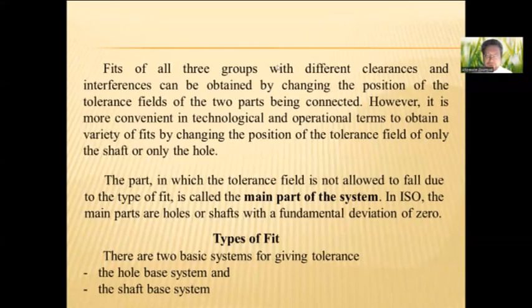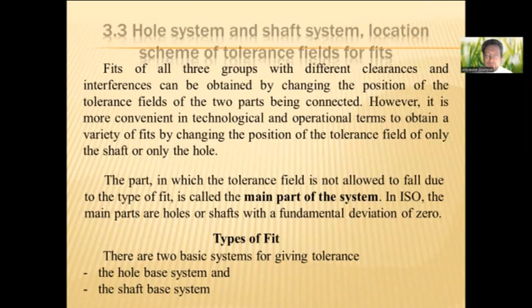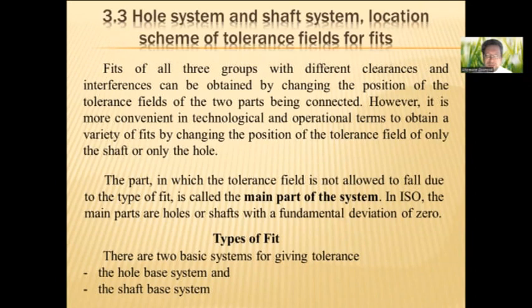Fits of all 3 groups. Now we start the next item of our lecture: hole system and shaft system, the location scheme of tolerance fields for fits. Fits of all 3 groups with different clearances and interferences can be obtained by changing the position of the tolerance fields of the 2 parts being connected.